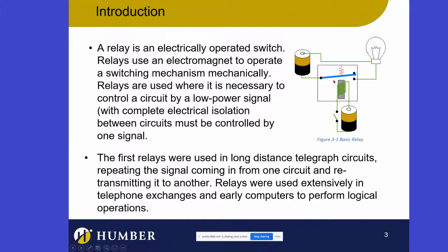So if you turn the electromagnet on, it's going to change the contact in a switch. As you can see, this is a single pole double throw switch. Up, down, up, down, up, down. Normally, because the concept of normally is this thing with this spring. If a switch has a spring in it, it has a normal state. So normally, this is the common and this is the normally closed.